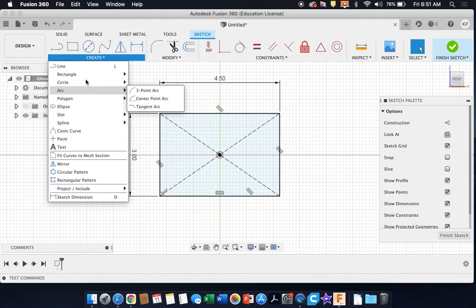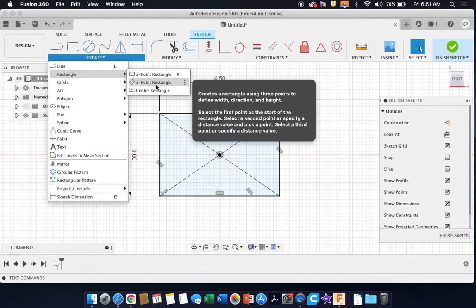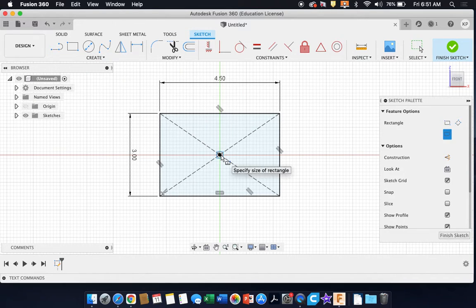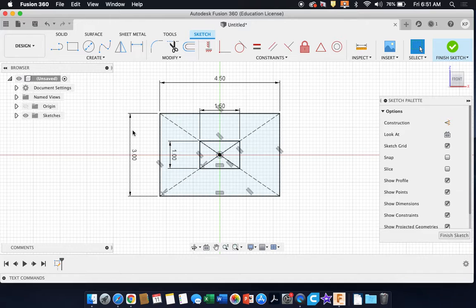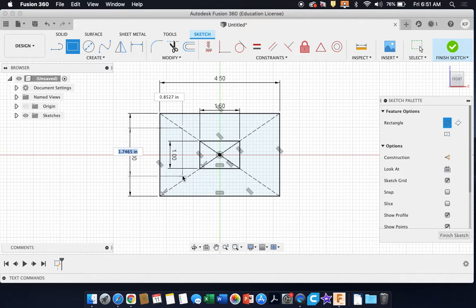We're going to do a second one of those. Center point, straight out, and we are going to go 1 inch tall and 1.5 wide. We're going to use our regular 2-point rectangle, which we can just use the R command for, and randomly in here, and try and make sure that they don't line up. It kind of throws in some extra constraints, so try and avoid that.